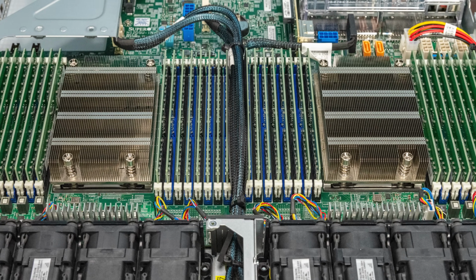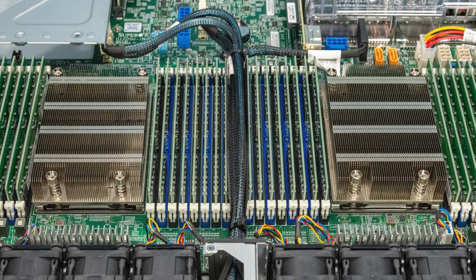And another area, just giving you an idea in terms of maturity, the early iterations of these immersion cooling tanks would just use a standard server. You just dip the server in and let the thing go. But now there are companies out there that are looking at things like, if you have a heatsink, well, your air-cooled heatsink is really designed for the fluid density of air. But if you have a more dense liquid, that means that you have different fluid dynamics. And so there are companies out there that are creating custom immersion cooling heatsinks that are designed to more efficiently move heat away from components in immersion cooling. So that's kind of cool and just shows you how mature the market is getting.